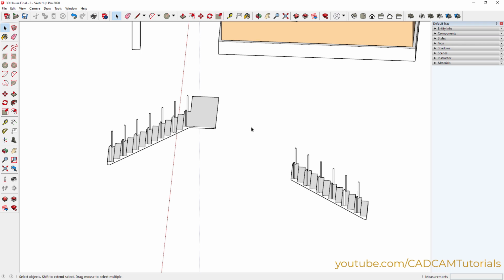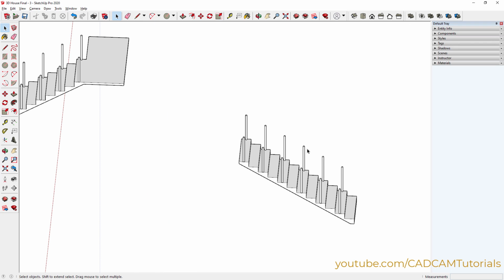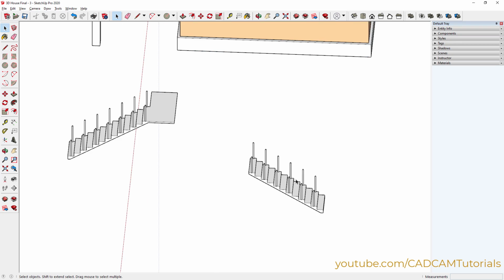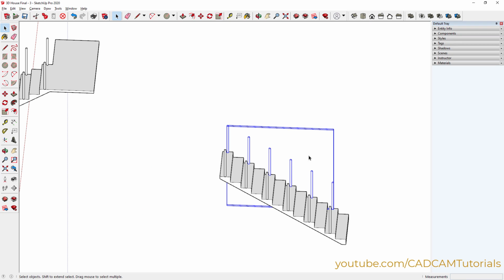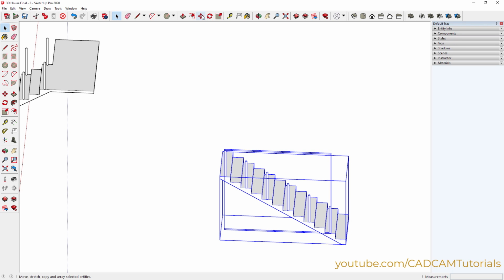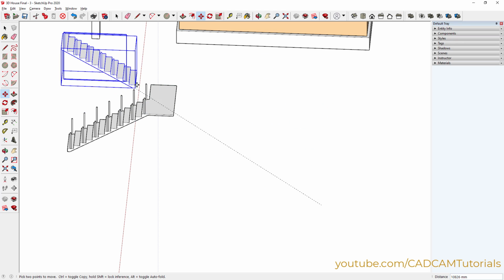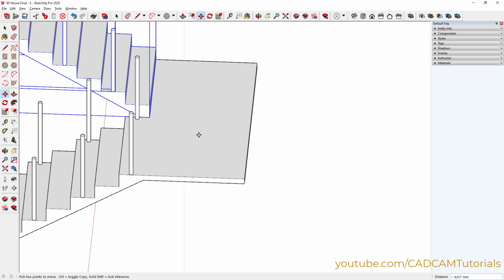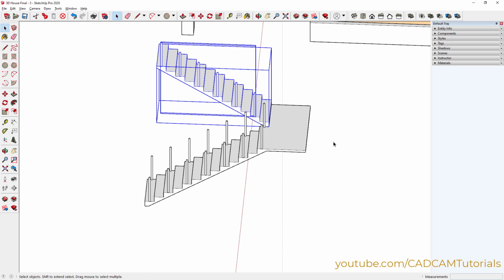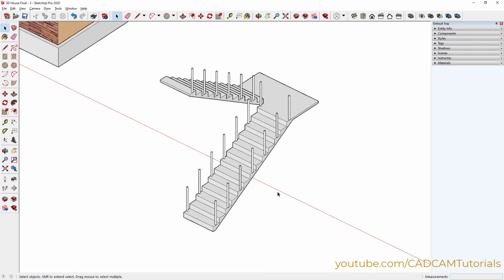And we want these steps on this point. So just select these steps. Before that, actually we will not need these pipes on this side because wall is there. So select these pipes and delete. Select these objects, click on move, select this endpoint and click on this endpoint. Press spacebar, click outside. So here steps, landing, steps, and we will need one more landing of 1000 size here.